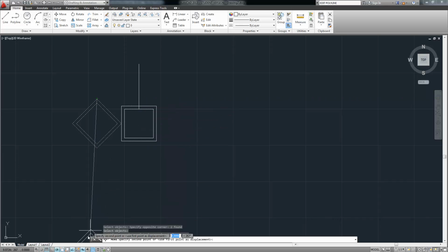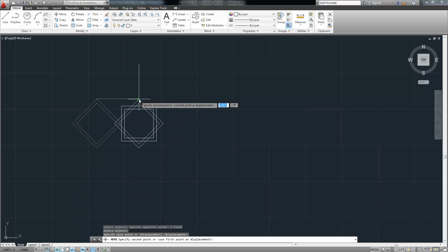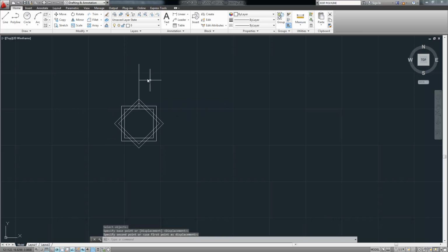But you see we want it to snap right on that line. It's got to be exact. So there's two things we can use. We could use nearest, which selects the nearest point on any line, or just to be safe we can use perpendicular. And there we go. And now let's delete that construction line.